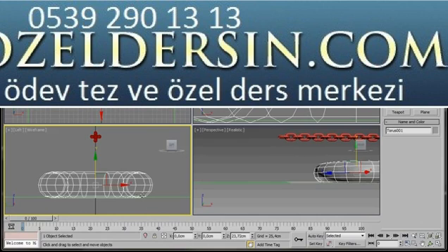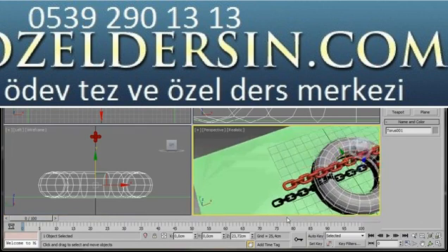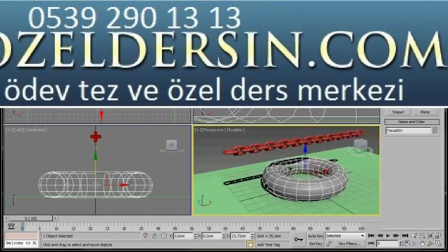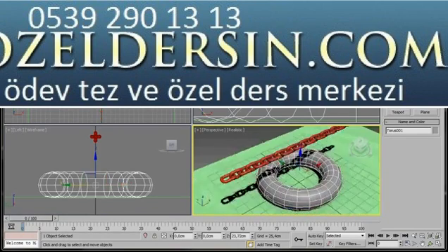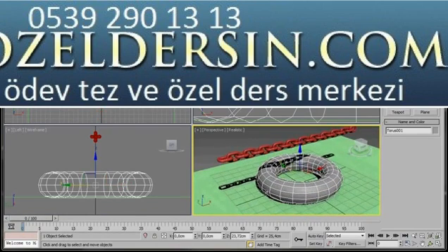Let's just pop into our perspective viewport and orbit around a wee bit. Now we can add the modifiers to these two last objects. Let's start with the torus first, select it, and we'll pop up to the main toolbar. Click anywhere in the middle of the icons, right click, and now from the menu, select the Mass FX toolbar. You can just leave the toolbar floating or anchor it. I'm just going to anchor it here.